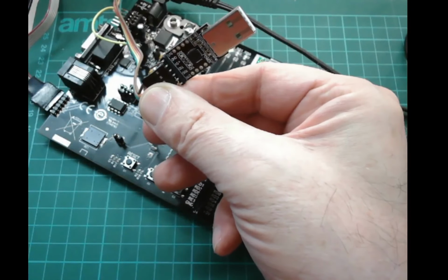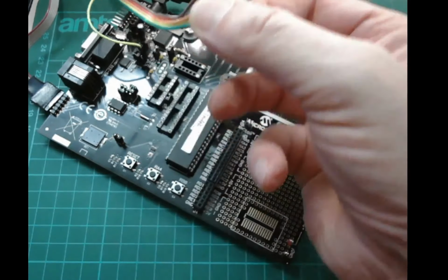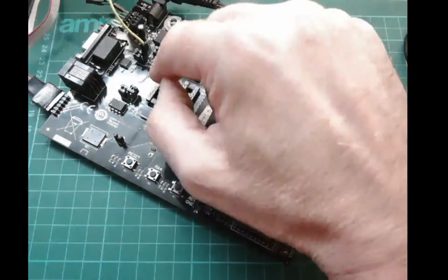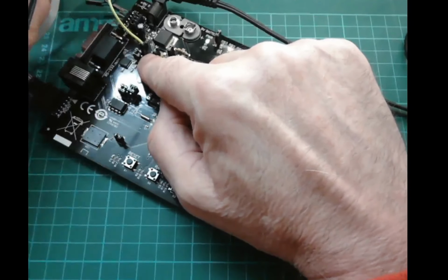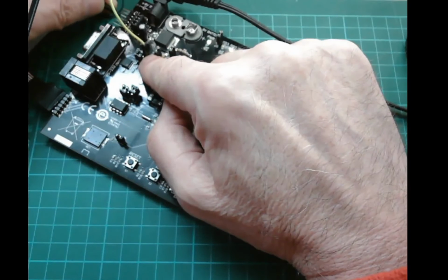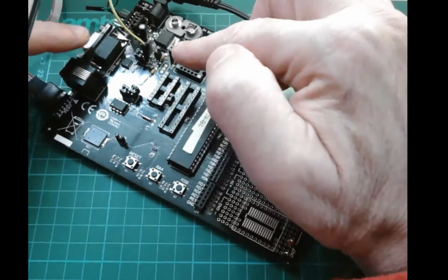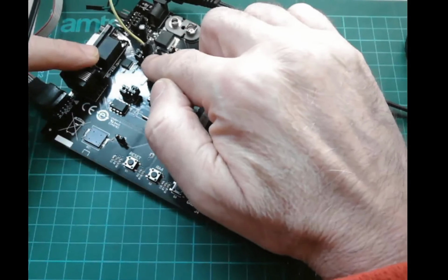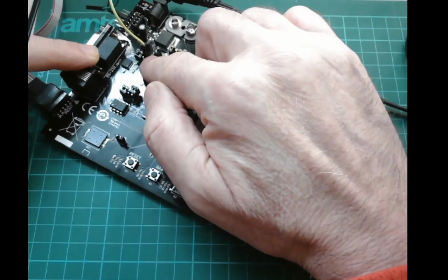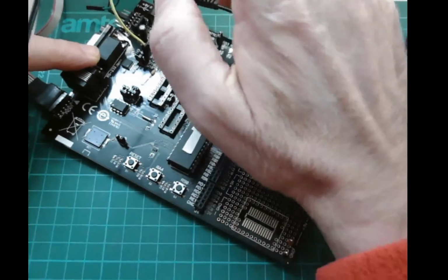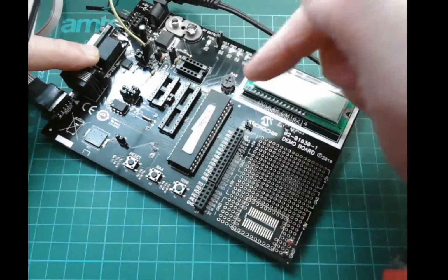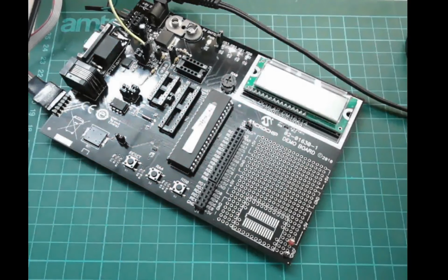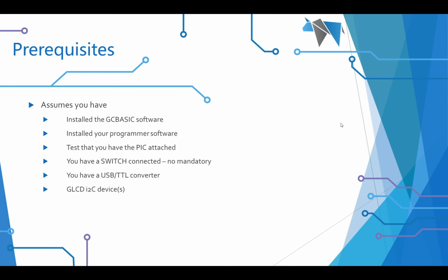It was connected, not anymore. Connected up, and I've got that connected to a serial line here and a ground line on the back of that rail. So basically, shortly, any serial connection stuff will just come out of here into my USB TTL converter, and then we can see it on the screen. It just makes it easier. And we'll look at that to sort of justify that.